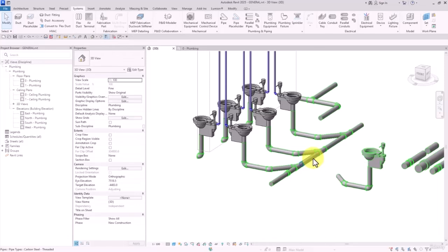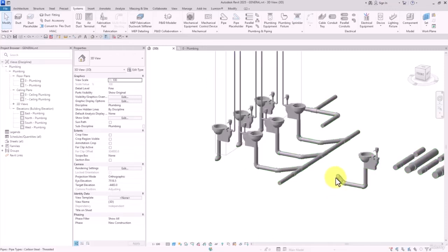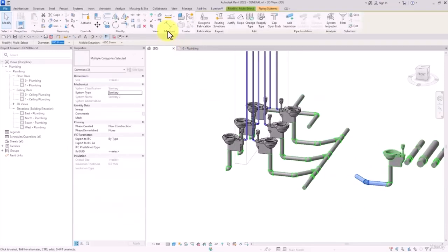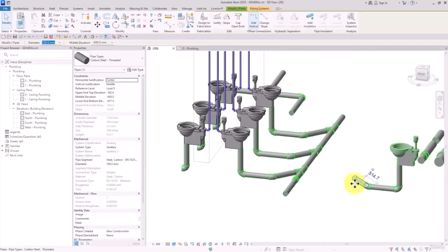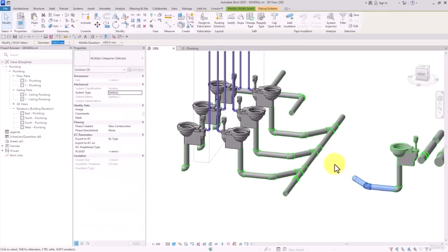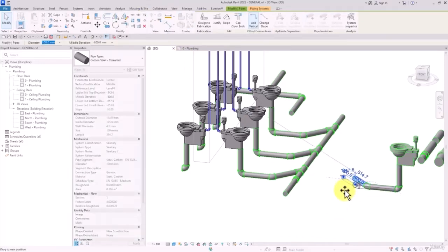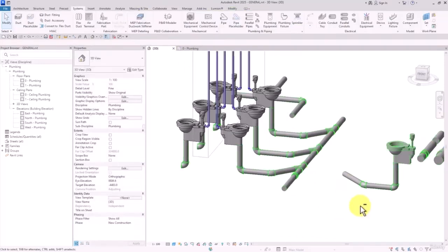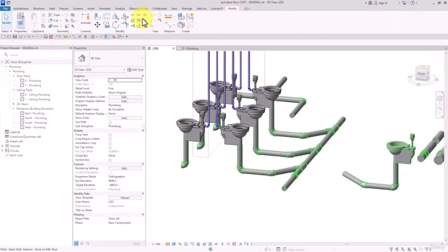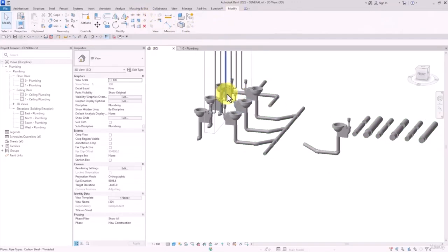So we found out what pin does for us. I mean, it doesn't let the objects go through any extra and unwanted changes. But what if we wanted to add some new modifications to them? Well, it's easy. We can reverse everything using unpin. See, now they are not pinned down anymore, and we can go ahead and apply any kind of new modifications that is allowed here. And yeah, that's it. These are all the important items that we have in the Modify segment in Revit software.